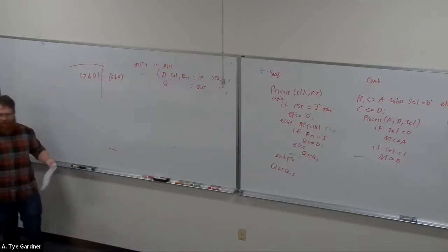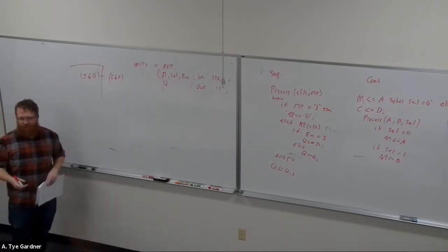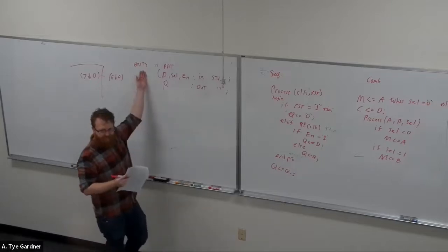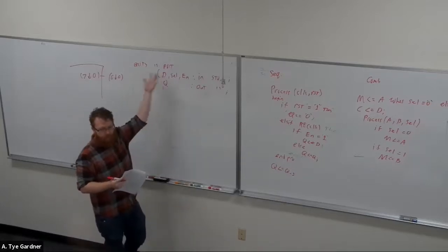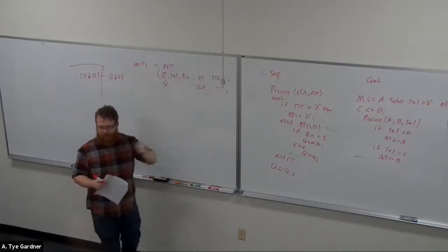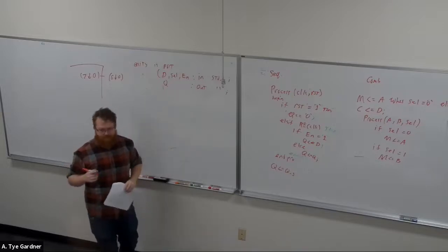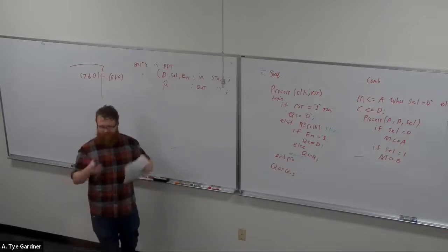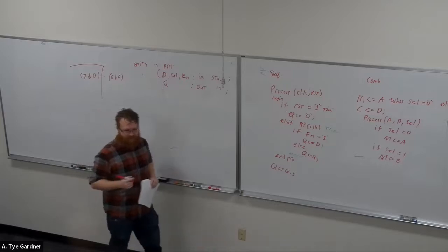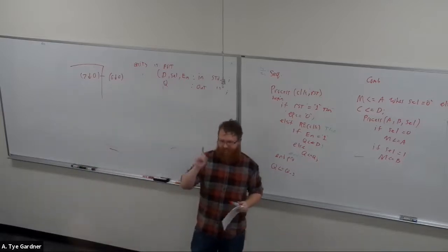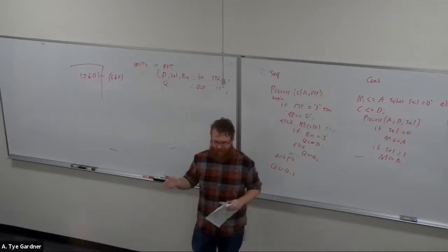Make sure that you understand the port map matching. If I were to give you two entities or component declarations, say, I'm gonna give you two component declarations and tell you to imagine that you're writing the top level module, connect these two together, write the signals and the connections that you need, write the instantiation and any signals that you need to make them connect, right?